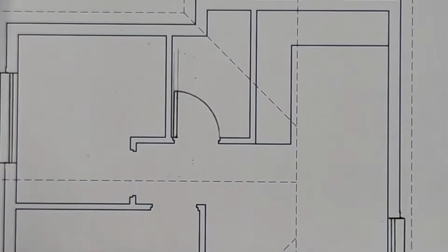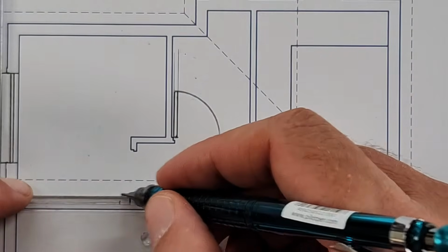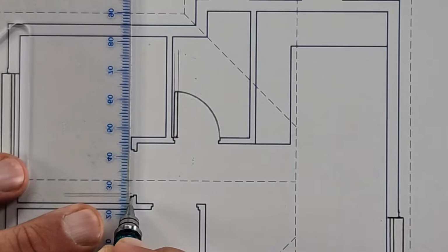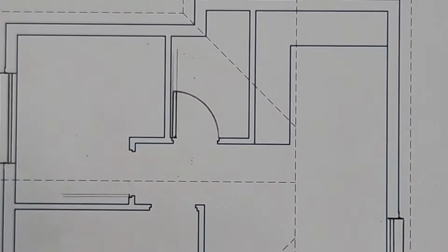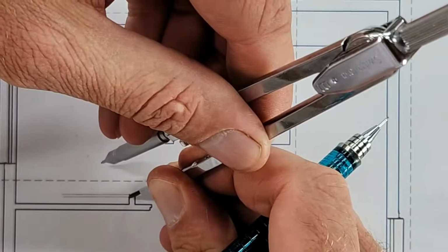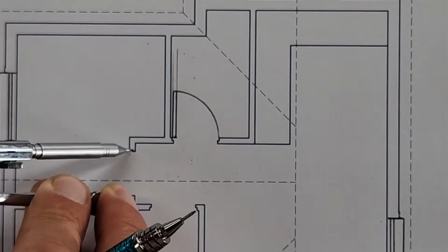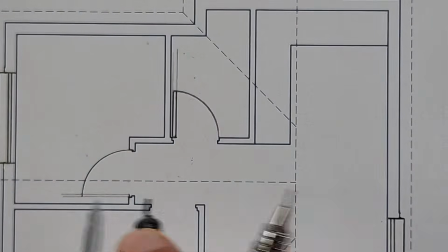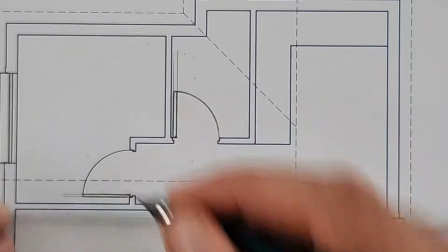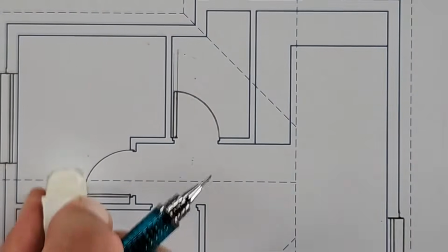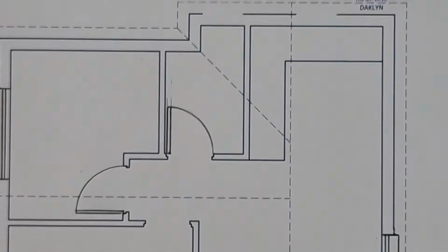Let's do the next one. So on that corner, construction line, same width. You can guess it if you have to, but keep it small. Draw my first corner right there. Now I know if I close it, it's going to fill into that gap. Take my compass on that corner where the hinges are, double check my size here. If necessary, make some adjustment. And my arc goes to the end there. Chip, chip. Takes you a few seconds and you've got that drawn with confidence. Happy? Alright, while we're at the bathroom, let's continue.